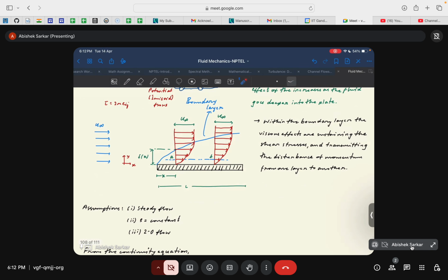Okay, so let us go through it, then I think it will be much clearer. This is how the boundary layer forms, and there is a clear demarcation between the viscous and the inviscid region. As I already told you, say we are considering the boundary layer at this point, the velocity at this point will be 99% of u infinity. I think I should mark it out so that it is clearer for the students. So at this point u is 0.99 u infinity. I think I should draw it at the other end where there is space.